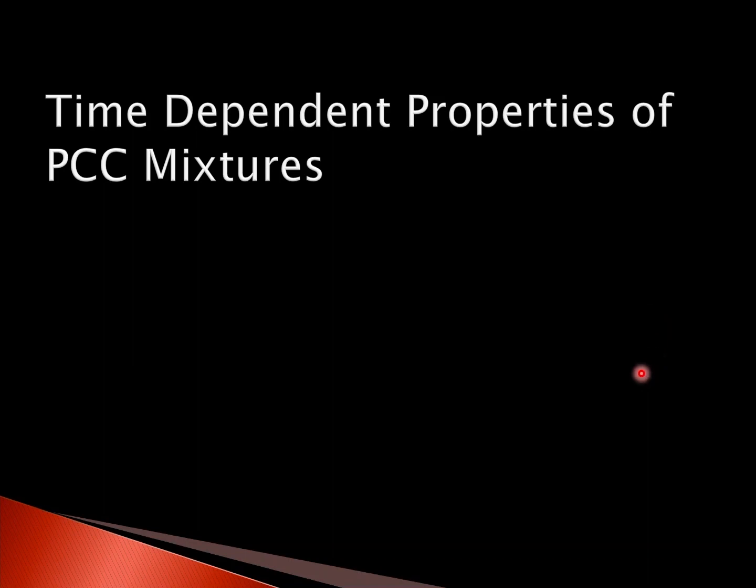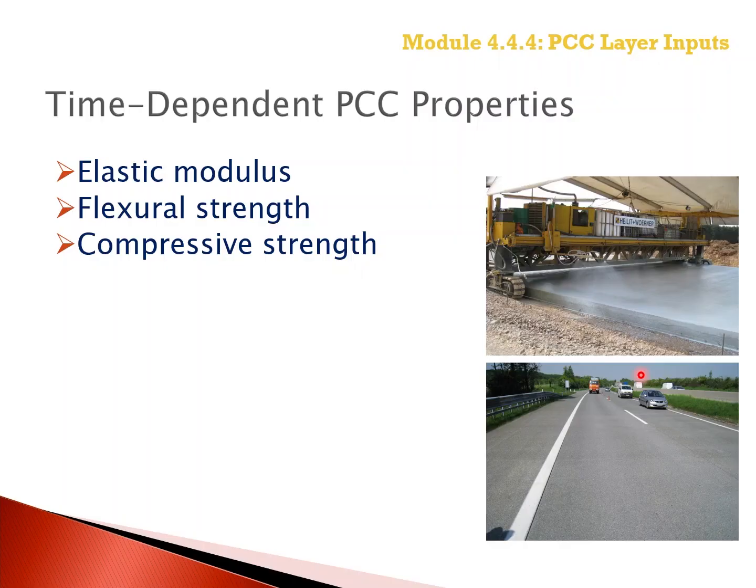So now let's focus on the important topic to understand how the PCC properties can change over time as simulated or considered within the PMED software, the time-dependent properties. It is common knowledge that the elastic modulus, modulus of rupture, and flexural strength and compressive strength of the concrete mixture will increase over time.